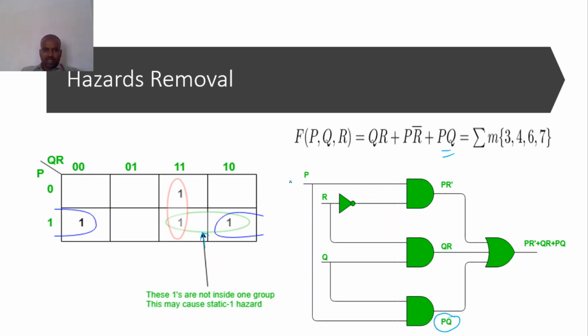So now the same concept 1, 0, 1. Now see here, actually our expected output is 1 now. Okay, so now don't bother about this NOT gate, whatever delay it is having. So this is 1 now. So whatever may be the output here 0 or 1, here 0 or 1. Have a look at this AND gate. So here 1 is coming and here 1 is coming. So this is 1. In OR gate, if any one of the inputs is 1, automatically the output 1 will come.